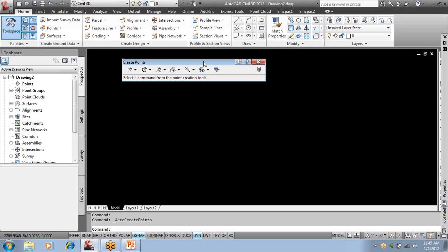But if you think about this current software you're utilizing, when you build a surface, what's that built off of? Well, it's built off the points that the surveyor went out in the field and collected. Hopefully they're all ground shots. If they're not, they're using a coding method so that I know which ones to exclude. I don't want the boundary. I don't want maybe a setup point. I don't want any point that doesn't utilize an elevation, or any point that wasn't a ground shot. So I can say maybe a mailbox or maybe a tree. Hopefully I talked to the surveyor by now. They know that they have to be ground shots.